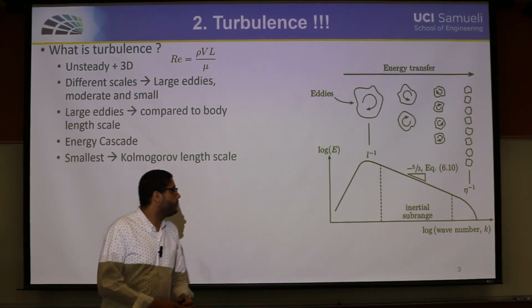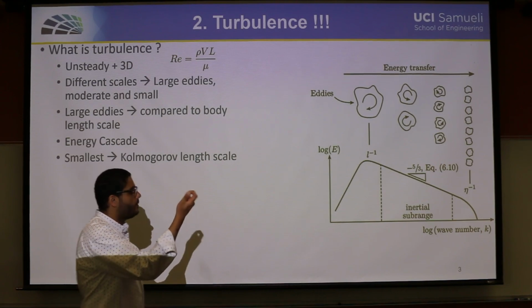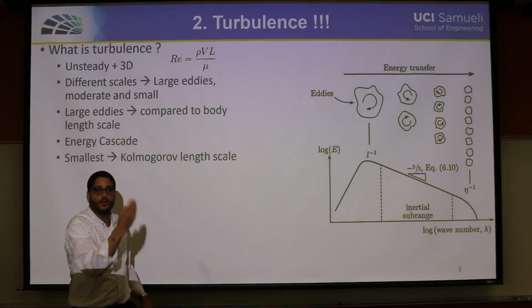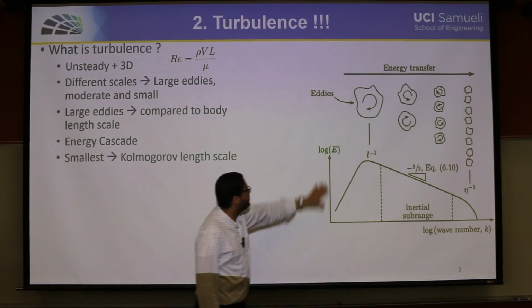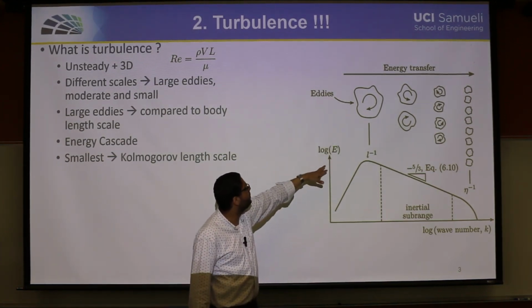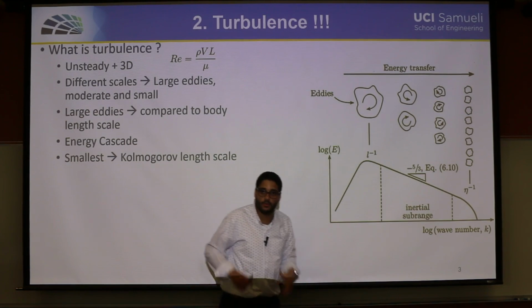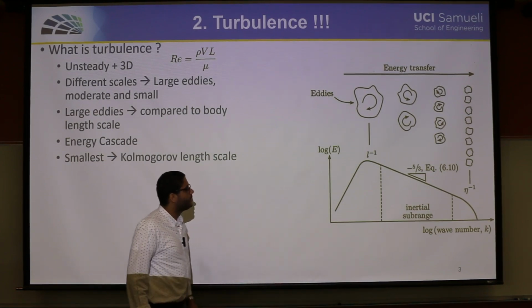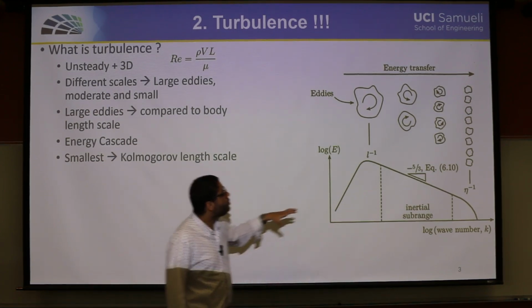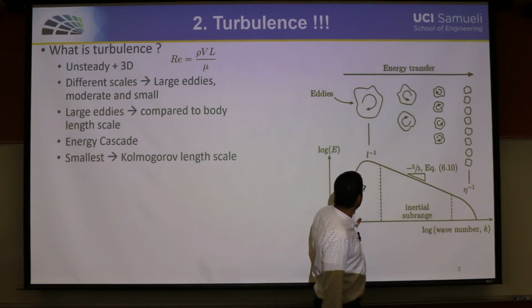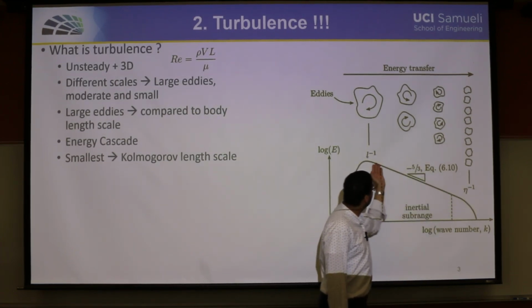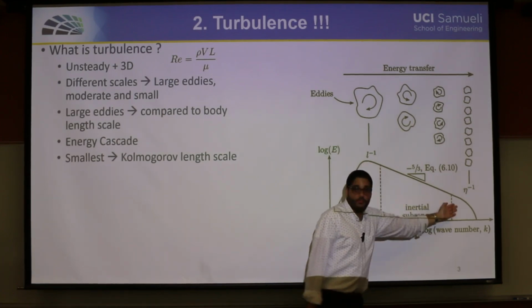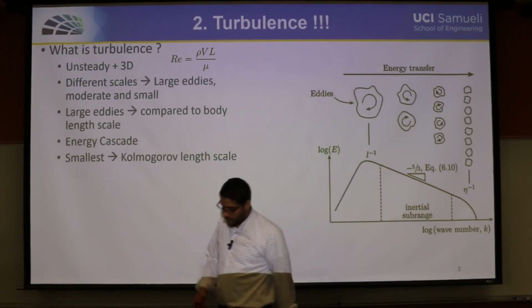In other words, if you brought a probe in your experiment, recorded the velocity, computed the kinetic energy and thus found the power spectrum density, and plotted this spectrum analysis, you will always find that the slope of that line is equal to -5/3.